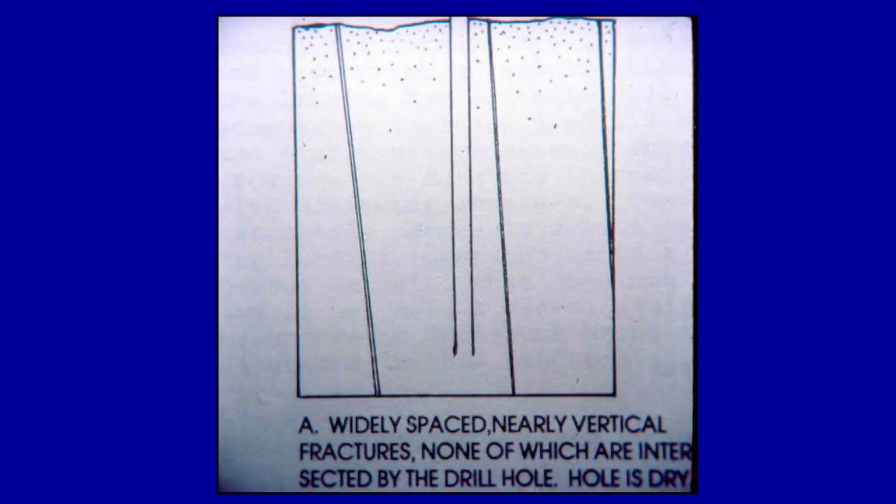As I indicated, most of the bedrock in New England is primarily igneous or metasediments, sedimentary rocks which have been metamorphosed. We have very few deposits of sedimentary rocks such as sandstones or conglomerates, and we have very few deposits of limestones. Therefore, the crustal fracturing of the Earth's crust has to present fractures which will allow groundwater to be stored and to yield. If in fact you drill and don't hit any of these fractures, you are not going to get a well that is going to produce much water.